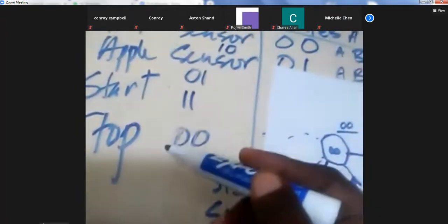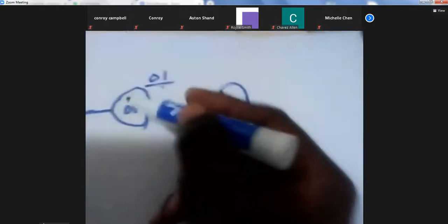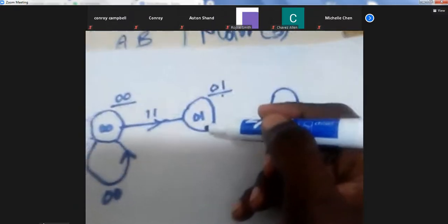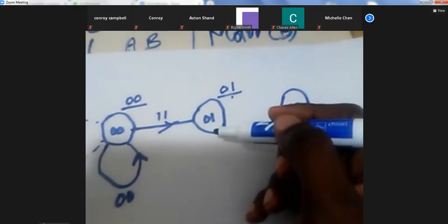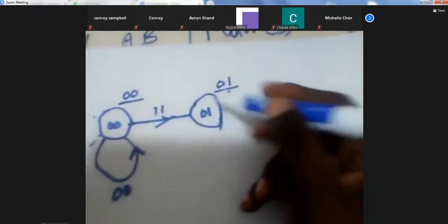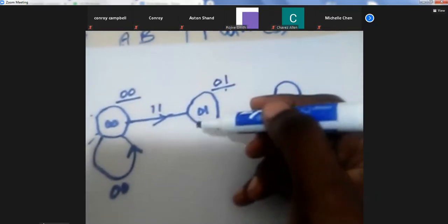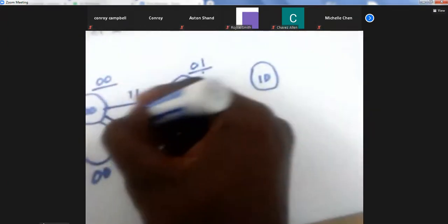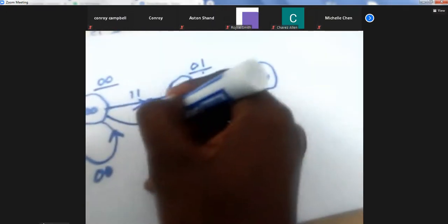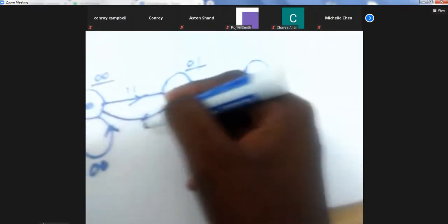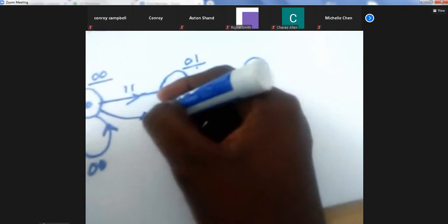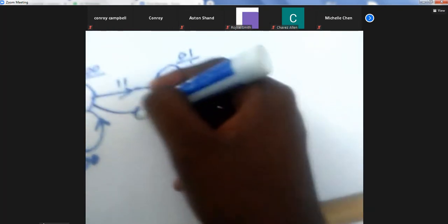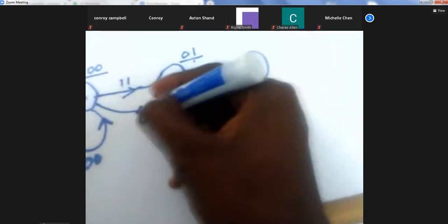So if I press stop, and I'm in state 0, 1, where should I go? If I press stop, I'm in the state where the box motor is running, and whatever happened, you're back to 0, 0. All right. If something happens, conveyor head get caught in the conveyor belt, and you have to press stop, then you go back to 0, 0.